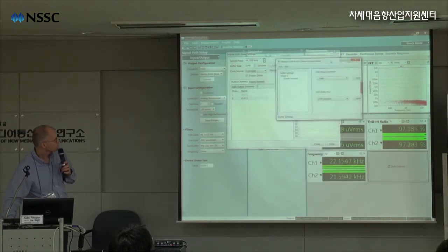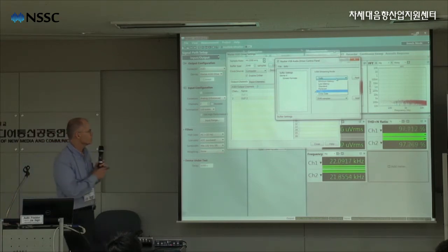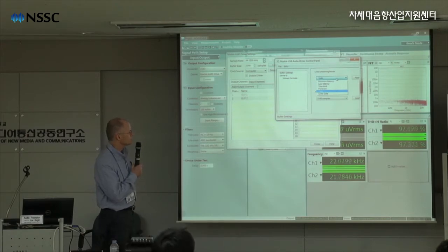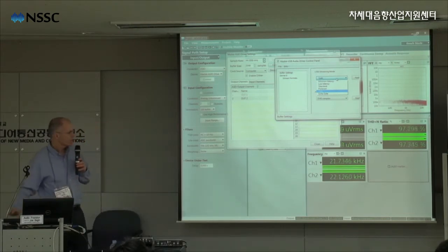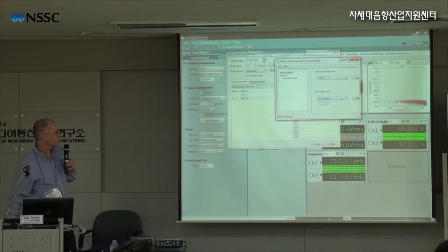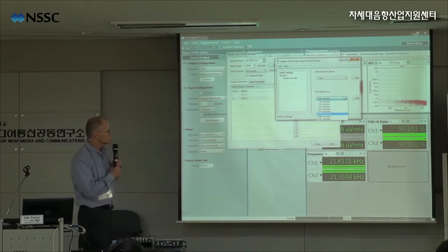And it's a very simple control panel. It just shows the device stream formats, the mode. So it's in safe mode currently. There are different modes available, like minimum latency, low latency, standard, relaxed, safe, and extra safe. And then you can choose a buffer size. These vary from 64 samples up to 8 kilosamples.